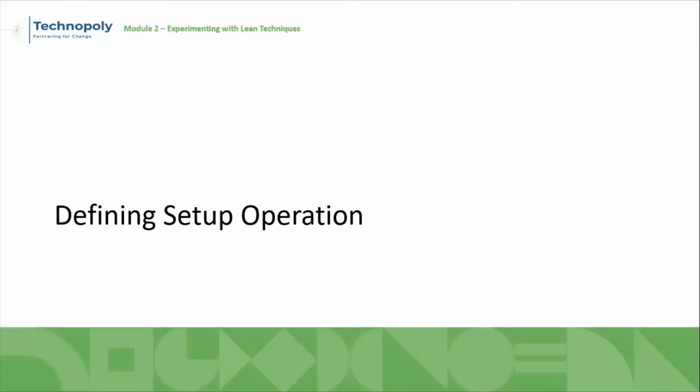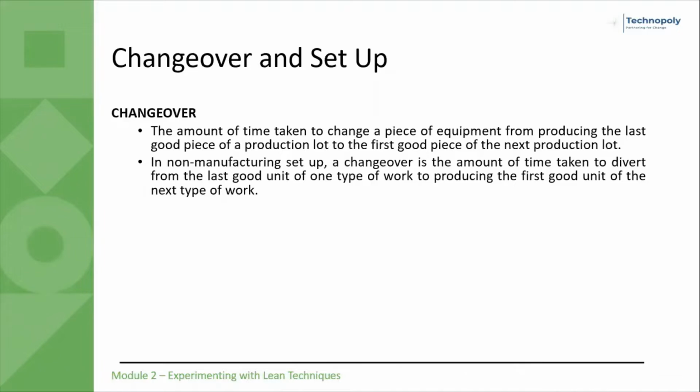Before going into the specific steps of SMED, let us first define what changeover is and what setup is. Changeover is the amount of time taken to change a piece of equipment from producing the last good piece of a production lot to the first good piece of the next production lot, as defined by Gemba Academy. In a non-manufacturing setting, a changeover is the amount of time taken to divert from the last good unit of one type of work to producing the first good unit of the next type of work.